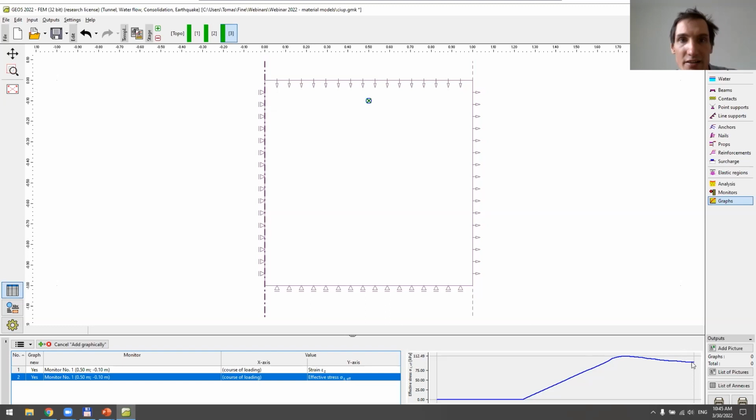Then when we shear it, when we start shearing it, the grains would normally contract, but because they cannot contract because of the water in the specimen, the pore pressure carries some of this prescribed chamber pressure, and the effective stress goes down, which is this decrease in the effective stress.